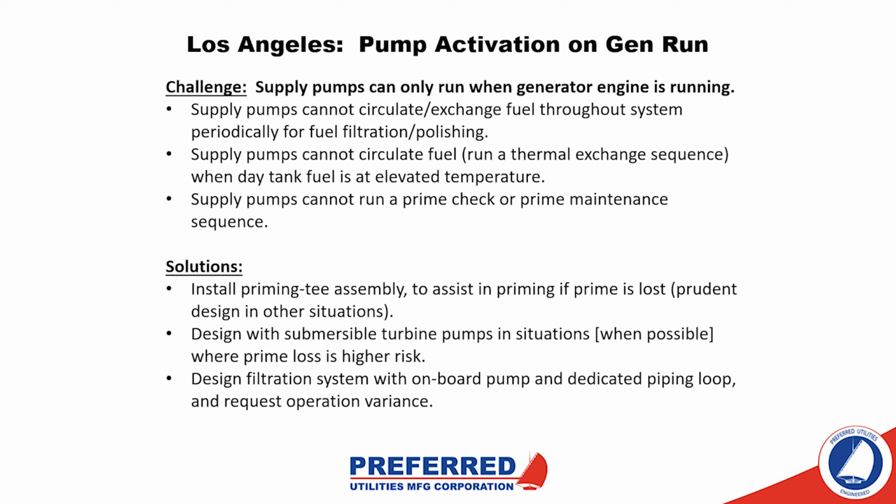Second bullet point here, supply pumps cannot circulate fuel, for example, when the fuel is at an elevated temperature, as we were talking about previously. We can have a sequence that we like to call a thermal exchange sequence that will, once again, turn over the fuel, say in a day tank that might have fuel that's over a certain temperature threshold.